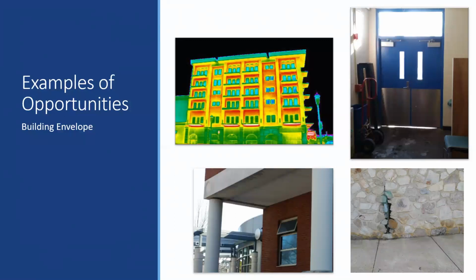Also, consider the doors. There is a lot of light and air infiltration underneath those doors. Anytime you see natural daylight under a doorway or in a window, you have airflow. And also in the bottom right, we have a picture of an exterior wall that has caved in. For reference, that wall hole is about 5 foot tall. It's about as tall as me. So if you have a space that big, consider what can move in, how much water you're getting in there, and what's happening behind that wall.